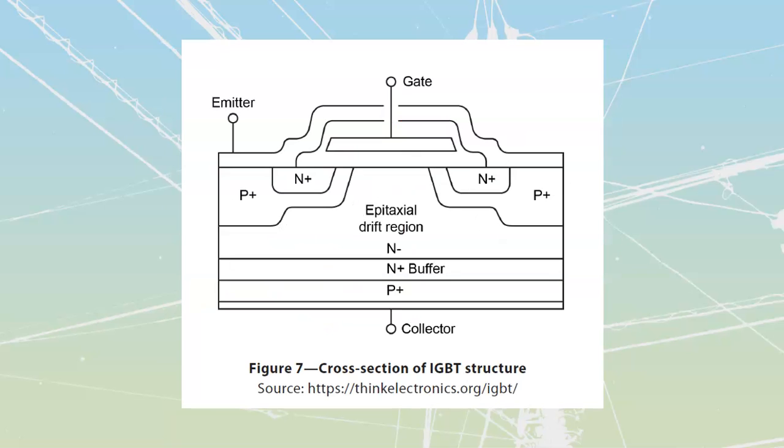Okay, next section that we've got to take a look at here is my IGBT, and IGBTs are much more common these days than they were probably even just 5 years ago. It's an insulated gate bipolar transistor, and it's a 3-terminal semiconductor device, similar to what we had for our FETs, but now it's going to be made with a few more layers. It has kind of a best of both worlds situation: extremely fast switching with super high efficiency, and we have 4 alternating layers now, NPNP. And then we're going to control them with an insulated gate that we're going to have up top over here.